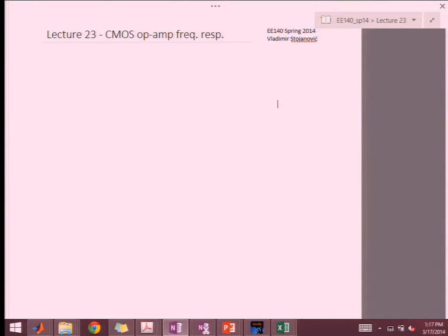So just over the end of the lecture, we sketched the folded cascade, which was one way for us to try to get a high gain amplifier without having to pay the price in very small output swing, or in other words, without having the need for very large power supply in order to fit the headroom of all these cascaded stages, right? Because remember, in telescopic, we had to fit like 2 diode stacks on each side, so to speak, to be able to get the output, right?